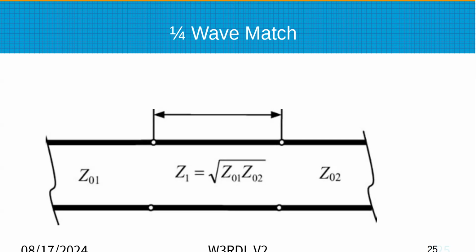If you had some different numbers, you might not be able to find a piece of transmission line that's the right impedance. So your choices are going to be, well, 50's out because you already have that. So you could do 75 or 300 or 450 or 600 with the ladder lines. If it's not one of those, then you can't really do it as a quarter wave transformer.